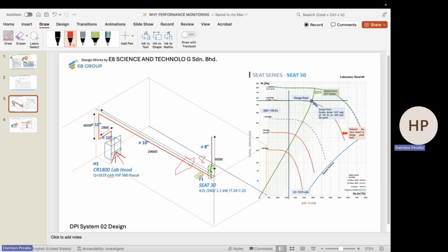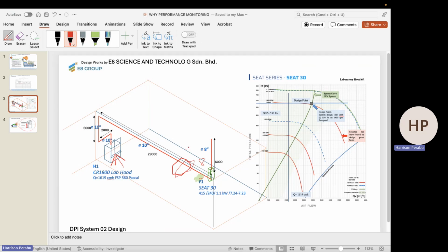Right? So now, when we put a filter, the filter will automatically have a resistance. Of course, when we design, we calculate the resistance. A bare filter, a new filter which is not clogged, assuming that it has a pressure loss of about 1 inch or 0.5 inch, for example 0.5 inch. Which means that when a fan runs, if it's delivering 8-inch static pressure, 8 minus 0.5 is going to be 7.5.